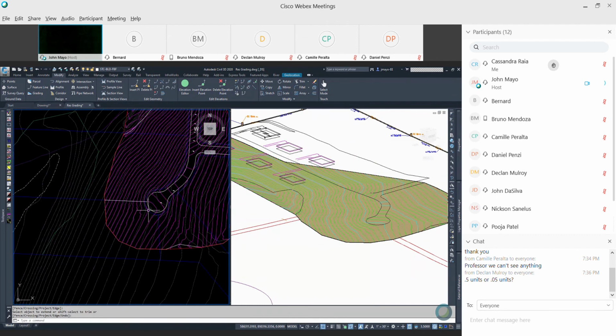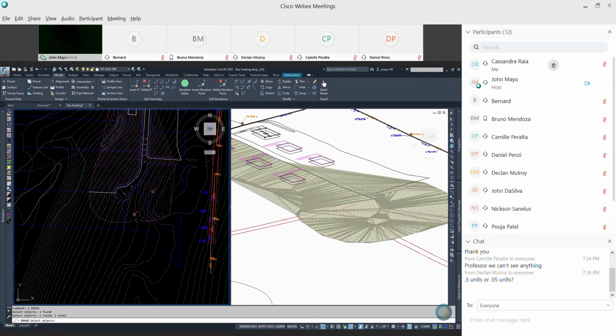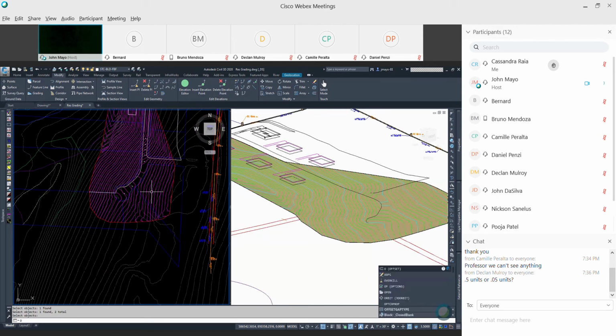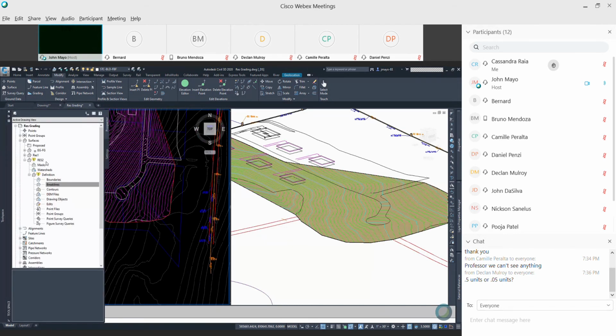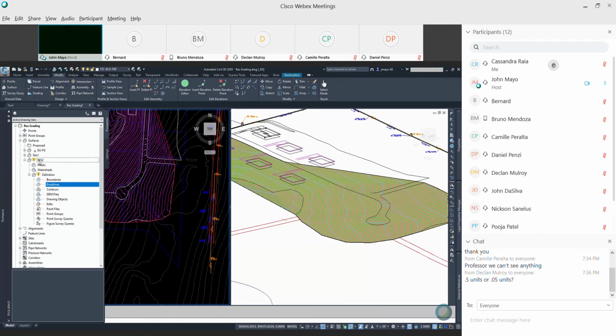So if I erase this and this lower one, and then run the oops command, and we've talked about this before, it is a command, and it will unerase the last object you put in there. Notice my surface is rebuilt because when I erased those polylines, they were removed from the surface. If I use undo, those break lines go back into the surface. If I use oops, they do not. So now if I rebuild,